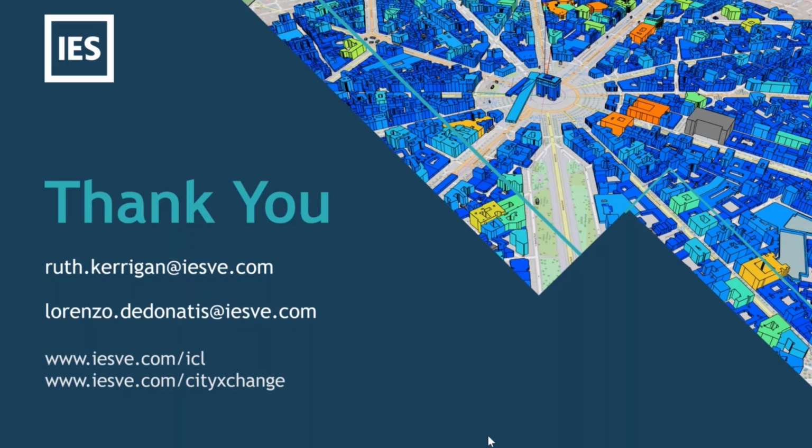Yes, the carbon factors used for the calculations come from the SEI values from the Irish standards. That's another important point: when you are modeling in a specific region or country, it's important to take into account the carbon factors of that region. Also, we were looking at final energy, but for a full picture you would also need to look at the primary energy factors of that specific location, which might guide you through the use of different sources.